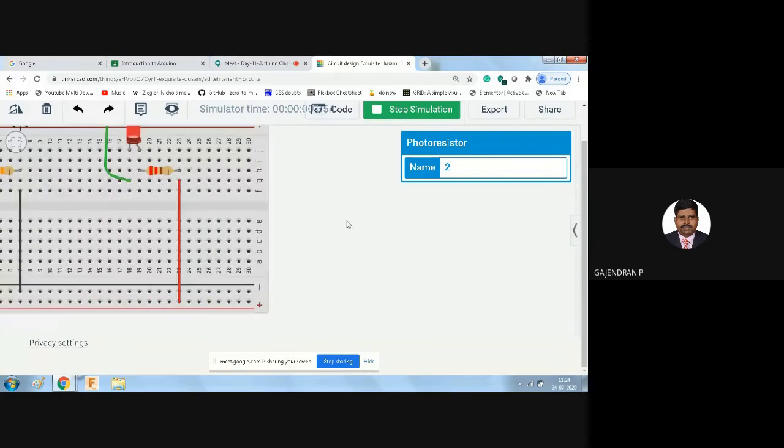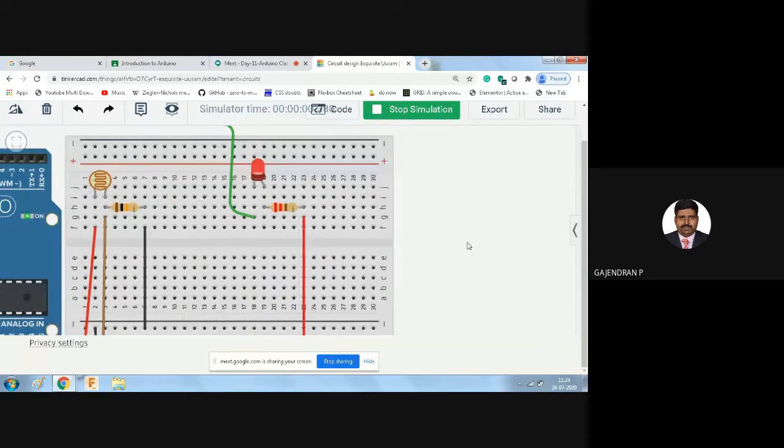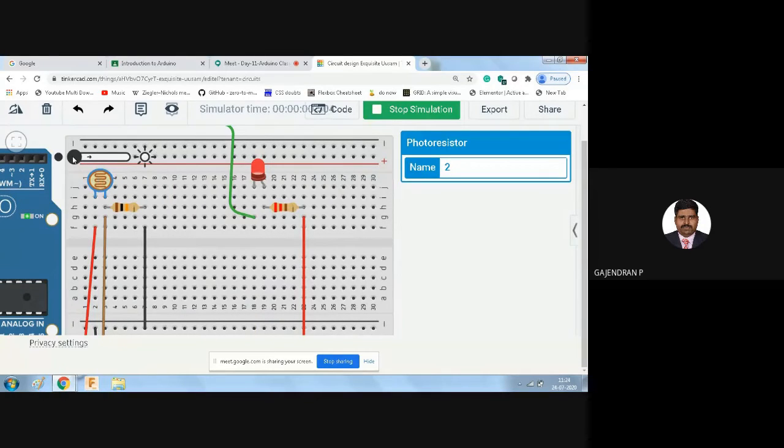So here we have achieved only the on and off state. If my LDR is in dark state, that means night condition, my lamp will glow. If it is daytime, full brightness, the LED will turn off. Is it okay for everyone? In this way, you can make the LED turn on and off. This is one task, where we achieve only on and off action.